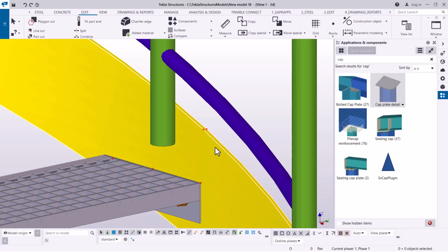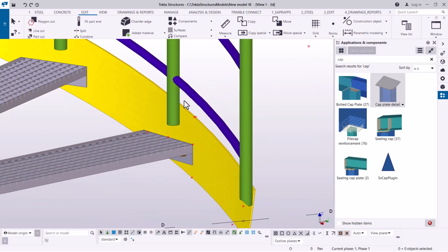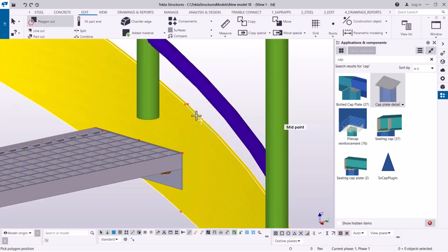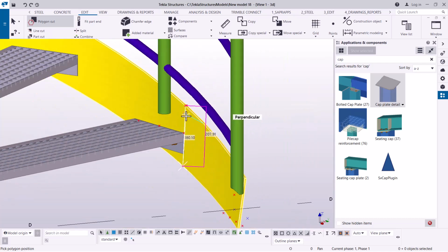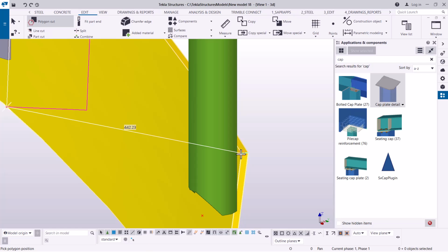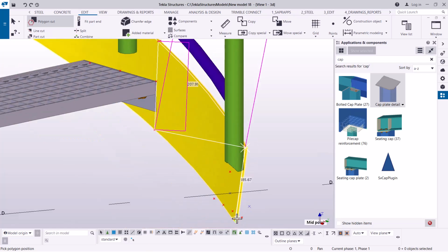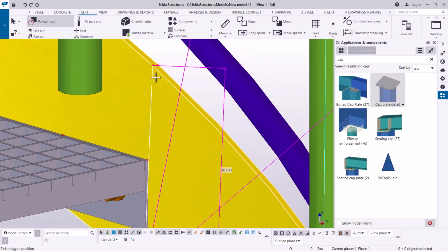It's somehow tricky at this point, so let's do something once again. Let me pick on polygon, and if I pick on that, I'll snap on that spot, snap on this spot, and snap on this spot here. Let's try polygon to trim it off, and if I use that, I'll be able to see whether we can trim it off.